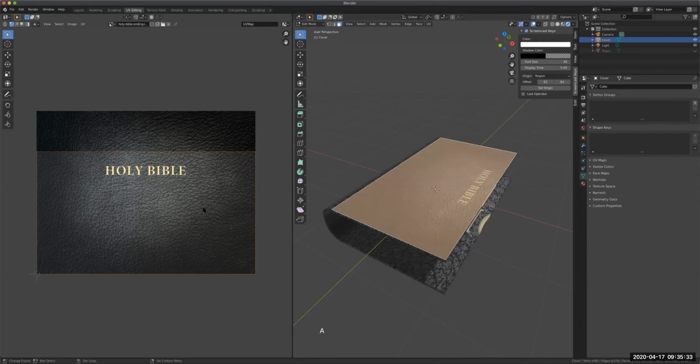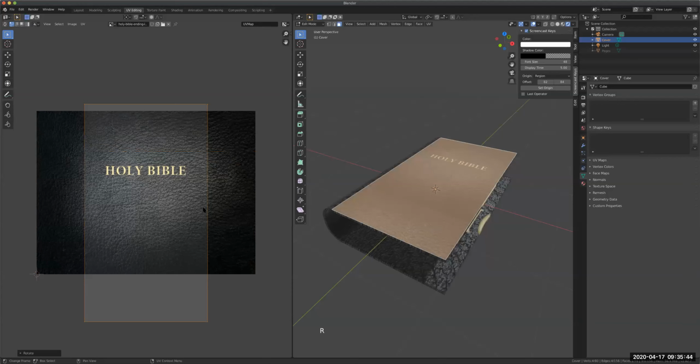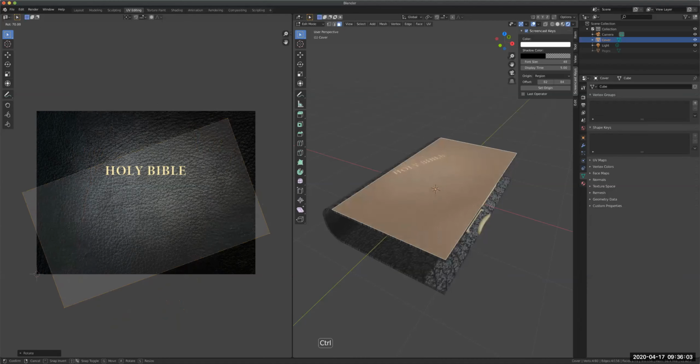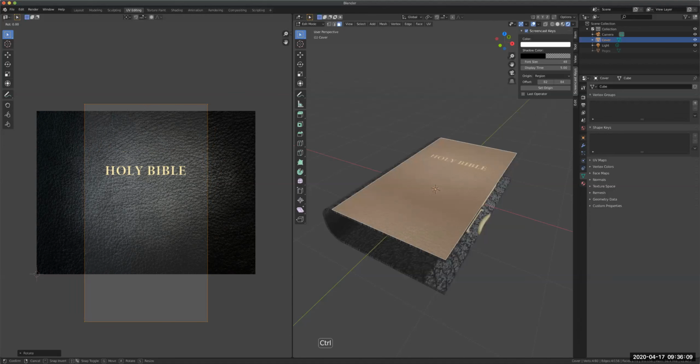Okay, now the orientation is wrong, so I can do rotation for this. The keyboard shortcut is R, and then we can type in 90 degrees, and it does that. Sometimes, depending on how you model, you might have to do a -90 so that it goes the other way around. Another way to rotate and have control is to press R and then hold down Control. When you're rotating, it goes in 5-degree increments. So you can for sure do a 90-degree, 45-degree turn, 180, and so on. I actually prefer that. It gives you a little bit more leeway.